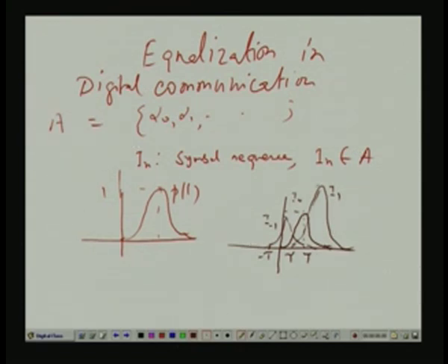To avoid that, we design the pulses so that at capital T, when I measure this one, all other pulses go through zero crossing. In general, you design the pulse so that at tau equal to 0 it is started, measured at capital T, then at tau you switch on the next pulse, and so on, and measure it at T plus tau.